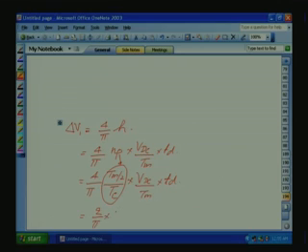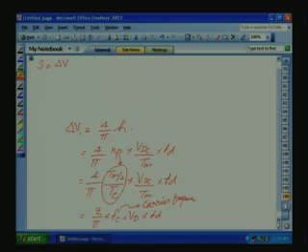This we can approximately write Fc into Vd into Td. Fc is the carrier frequency. So what it shows? It shows delta V1 increases with Fc for a fixed dead time.